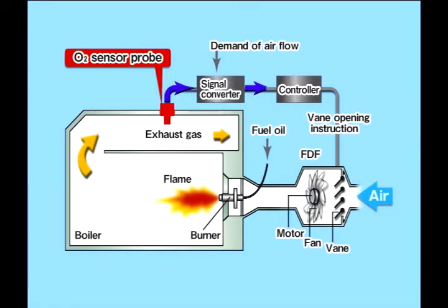The excess air takes heat with it as it is exhausted. Furthermore, excessive ventilation also increases NOx emissions. Proper FDF ventilation can be determined by measuring oxygen concentration in the boiler exhaust gas. The oxygen analyzer needs to be warmed up for 5 to 10 minutes before being used, so make sure to turn the analyzer on before operating the boiler.